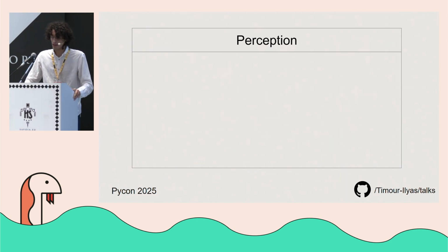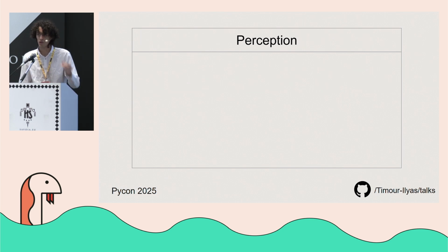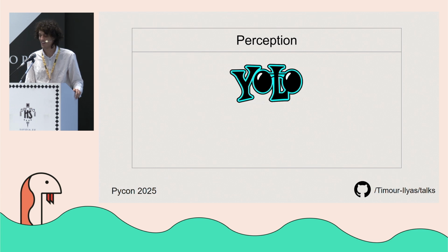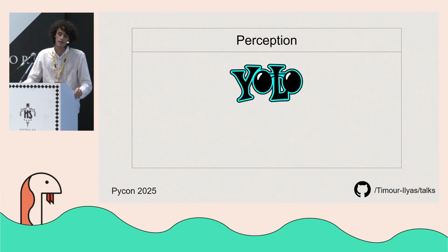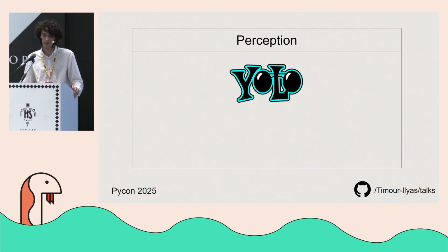And so in the perception module, actually, there is a strong standard, because YOLO is the main deep learning model used in this context, simply because the car goes at high velocity, especially racing cars. And so in this context, we need the best ratio between object detection precision and also the speed of calculation.